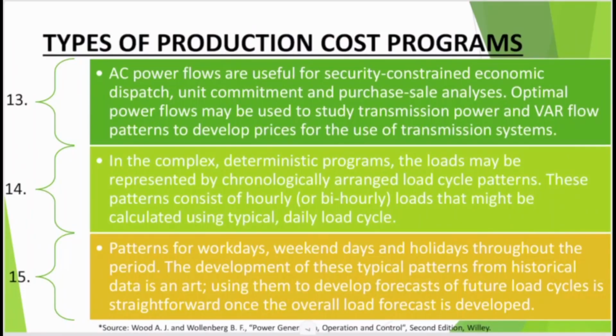So what we wanted to highlight here is, if you consider the transmission models even in your production cost programs, then the real and reactive power flow will decide the cost of real power as well as reactive power. In the complex deterministic programs, the load may be represented by chronologically arranged load cycle patterns, and these patterns consist of hourly or bi-hourly loads that might be calculated using a typical daily load cycle.